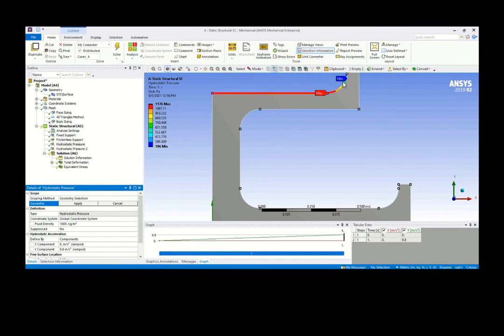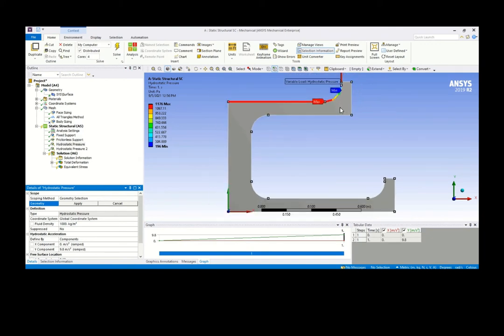Moving the waters, okay? This curve and this curve, right? Then we have to put in the fluid densities, water. Then the acceleration here is basically 9.8 in the y-axis, which is our gravity. Then we have to put the locations, the free surface location. Where is our free surface location? Meaning the top layer of our fluids. So we need to define these coordinates.